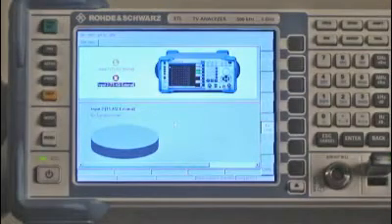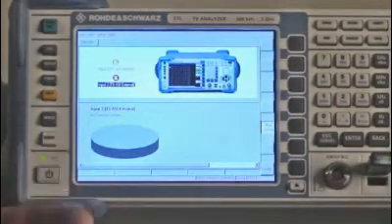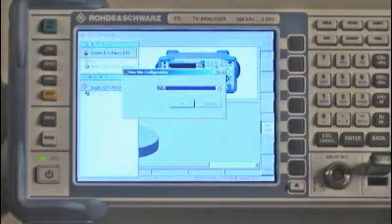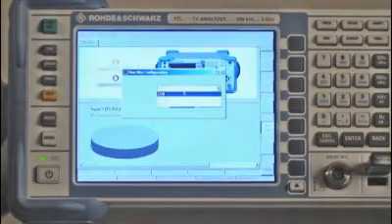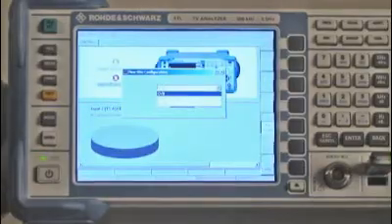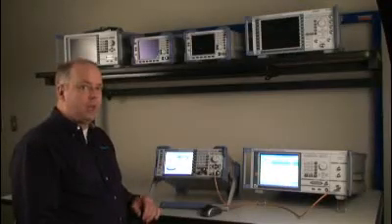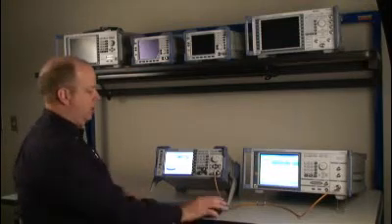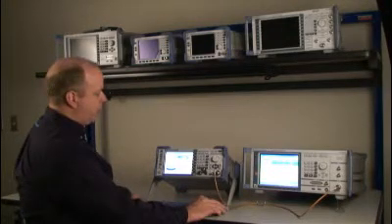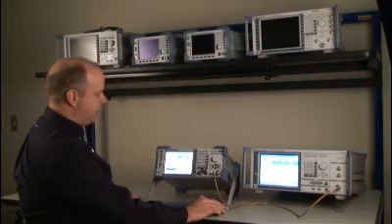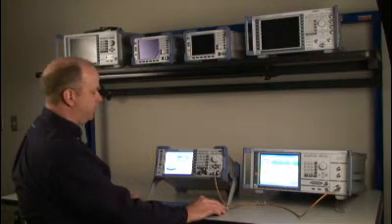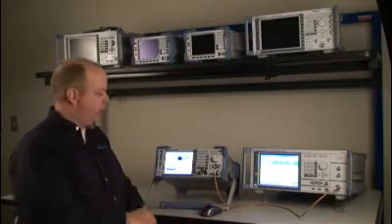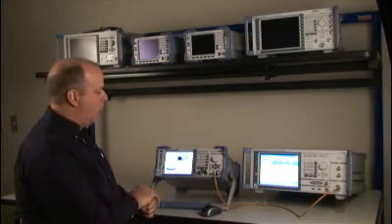The next thing, to ensure that I'm operating and measuring on the right standard, I want to come up to File, New Site Configuration, and change the site configuration to either DVB, ATSC, or SCTE, depending on what I am doing. Since we're talking predominantly about broadcast, I'm going to be selecting ATSC. Confirming OK as I go through there, and then it'll load up.